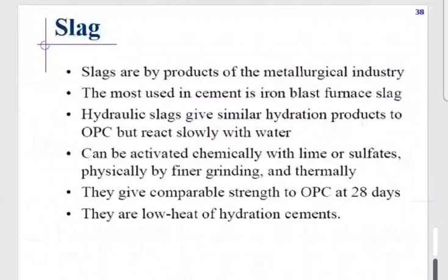Whenever you go for the research, you don't find the results, you find out something different, and students prepare some different stories about that. Clear? So what is the best way? The best way to start with the fly ash, actually you need to first of all characterize it. Get its SEM done, get its chemical composition done, get its particle analysis done, so that you can very strongly say that this is fly ash or not, and then you use it.